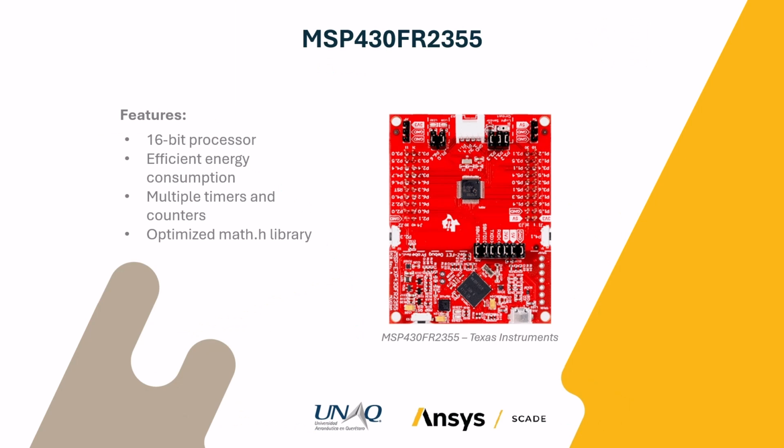For the project, I will use the MSP430 FR2355. The MSP430 family from Texas Instruments has an architecture focused on power consumption and efficiency. Its peripherals are activated only when needed, featuring a flexible clock system and advanced power management technologies. In these microcontrollers, hardware modifications have been implemented to prevent current leakage, along with software library adjustments and new architectures for energy management.